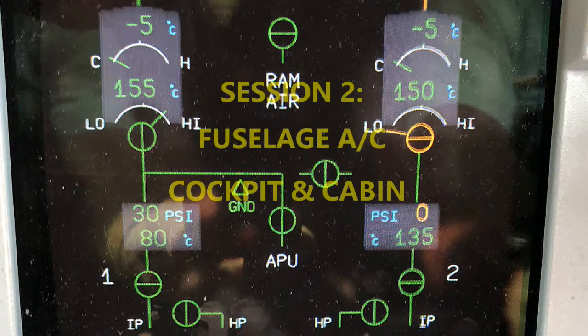But the secondary computer on the zone controller is responsible for keeping that constant temperature. Okay, primary is in charge of valve opening and closing, also failure analysis, your BITE, data handling, overheat detection, all of that type of stuff. And the secondary can do the same thing as well. What it won't do, okay, is the flow demand optimization. That is something that the primary computer strictly does. Same thing with the trim modulating valve control. That's strictly the primary computer's job.